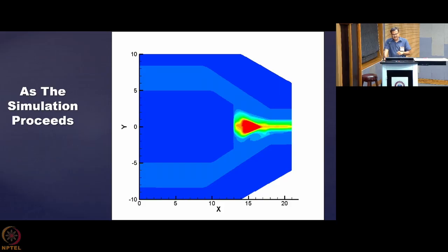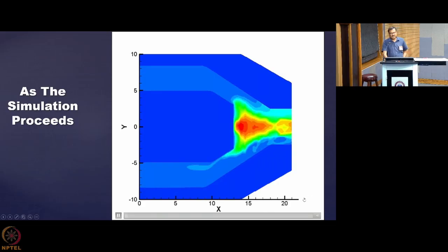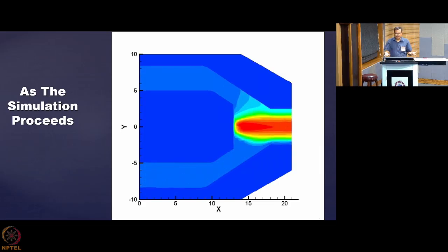Okay. Now, I just wanted to show you how the simulation proceeds when you change the geometry, because you have already seen the simulations that we showed earlier. Here we have changed the geometry: it is a straight nozzle but with a much higher diameter. See, previously you saw that it was quickly converging. Now, when we have increased the diameter, it initially showed a much wider jumping in the solution.